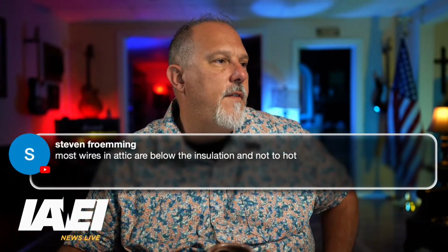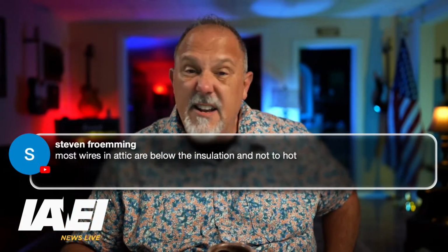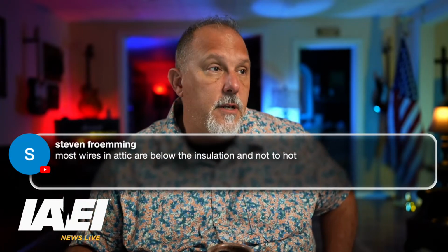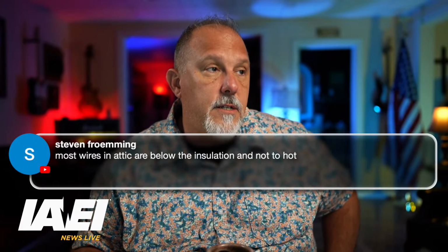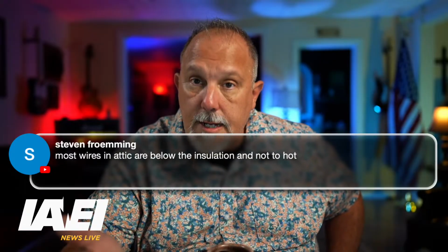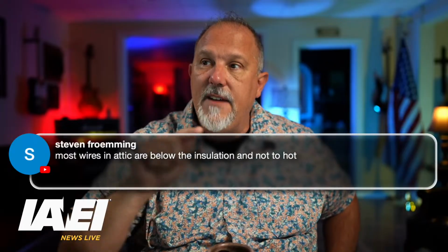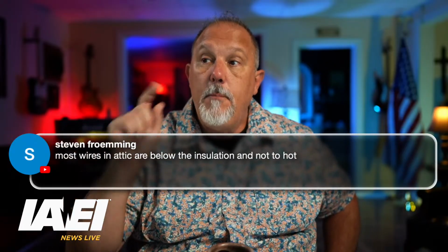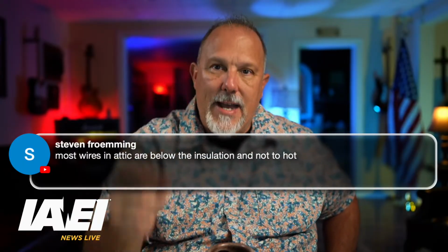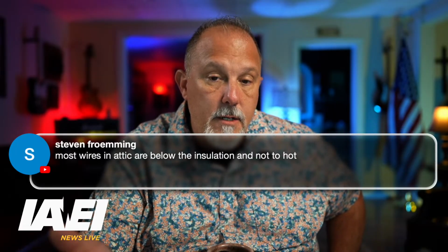If I do 90 degrees C, 90 degrees C is 194 degrees Fahrenheit. And I would agree, if it's below the insulation, 194 degrees is still hot. So if it was 150 or 140, it's pretty hot. And Steve, you would have to adjust the ampacity because that 90 degrees C insulated conductor, the ampacity is based upon 86 degrees Fahrenheit, right?